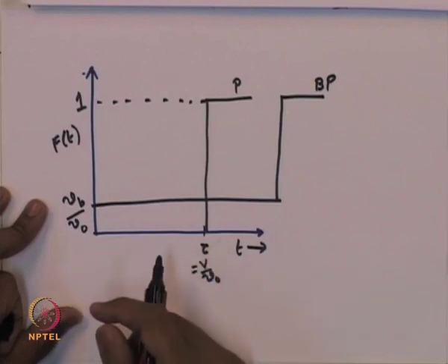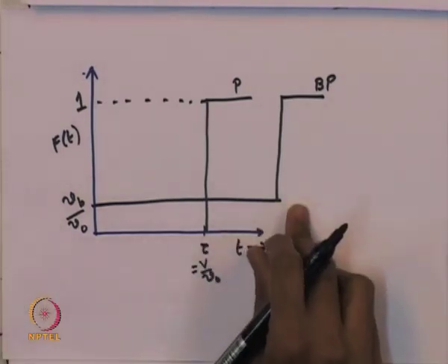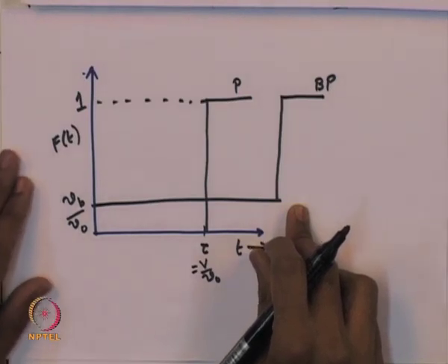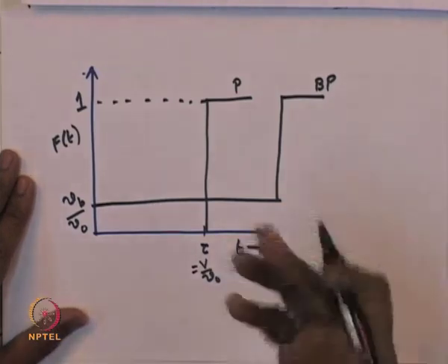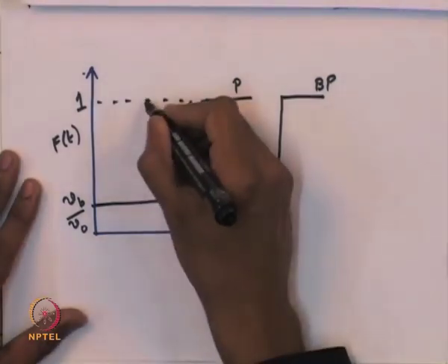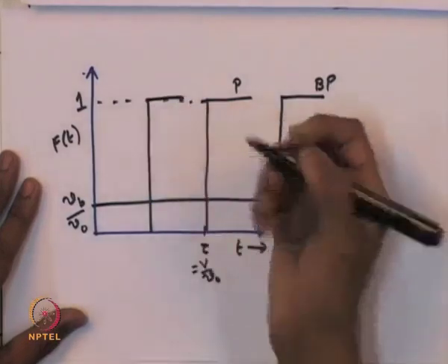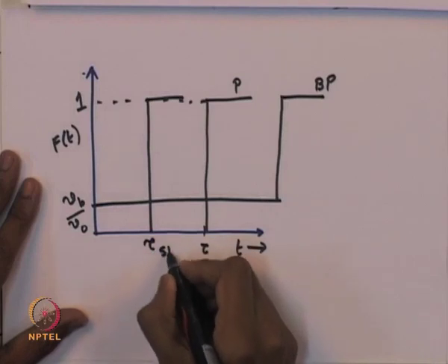And then if there is a dead volume present here, then the net active volume which is available for the fluid stream to access is smaller than the actual volume of the reactor. Therefore, the apparent space time of the reactor is going to be smaller than the space time of the plug flow reactor operated at perfect conditions. So, the fluid stream will leave faster than in the normal or perfect operation of the reactor. So, this is tau St.